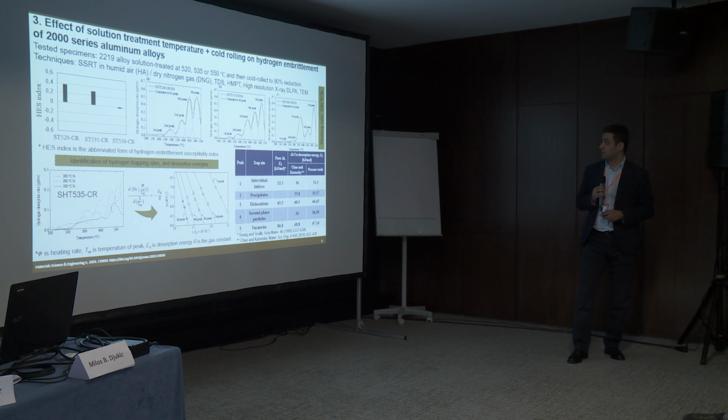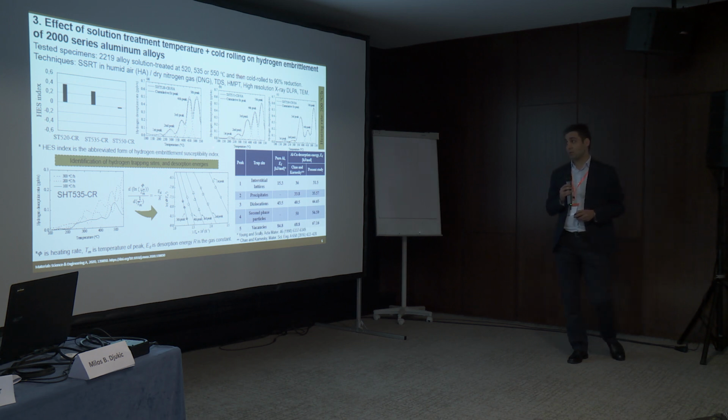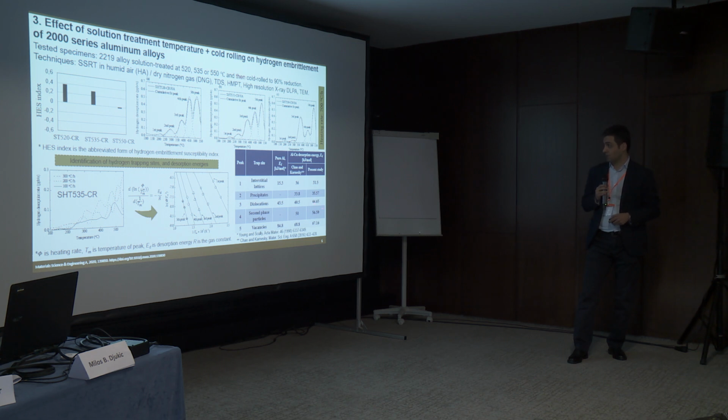This is a very good step to design a good alloy, especially when you can see that the force peak can be related to the second phase particle, and these second phase particles can change with the heat treatment. A higher amount of them can eventually be interesting for us to capture more hydrogen, because it has high energy here, as we can see.